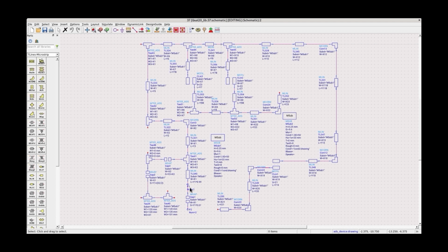We have to place both positive and negative pins in the schematic. The positive pin goes to the feed and the negative pin goes to the ground plane. We will see this in the layout later. When the microstrip line component tags overlap, we must separate the component tags because we will later edit the component parameters. Editing becomes easier when you clearly see the component tags.